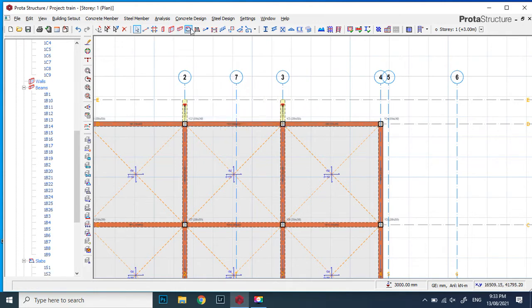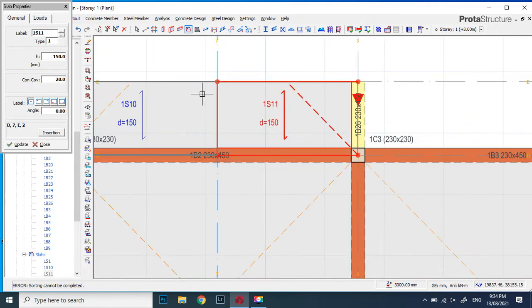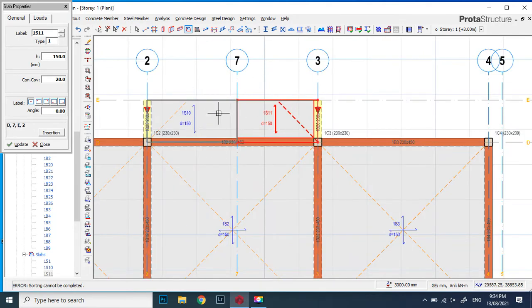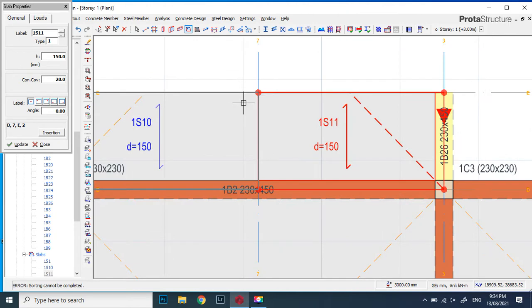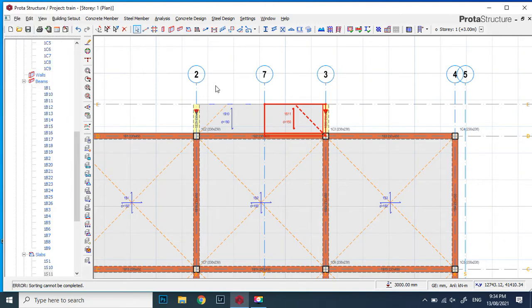Delete. So if you click your slab and you try to place it as the cantilever, this is what it will bring, which is not really good, because it's showing you a one-way slab where part is coming here and part is going out, which is not the right pattern for this cantilever, and will not give you the right answer. So how do you solve this problem if you encounter a problem like this? Please pay attention. This is very important.